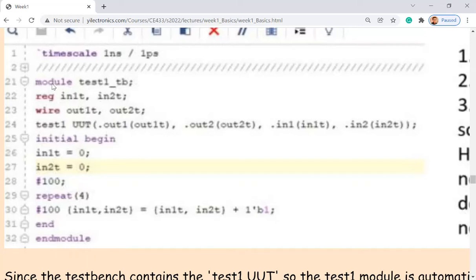It's a very similar syntax. It's a module, but doesn't have any ports. It doesn't mean that you don't need the ports for the test benches. It's just we are not implementing this on the FPGA. So we are not using the clocks, the switches, and LEDs for the test bench. These are just the internal signals being directly injected into the sub-module, or the unit under test.